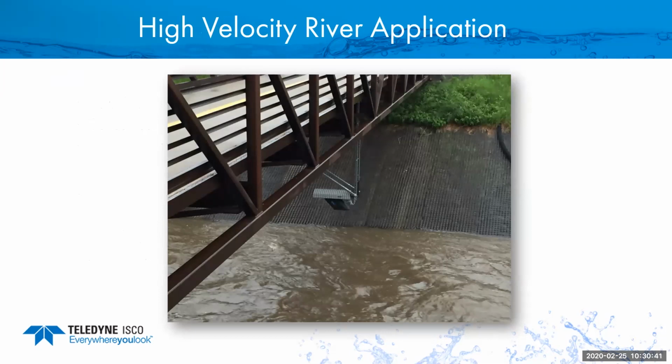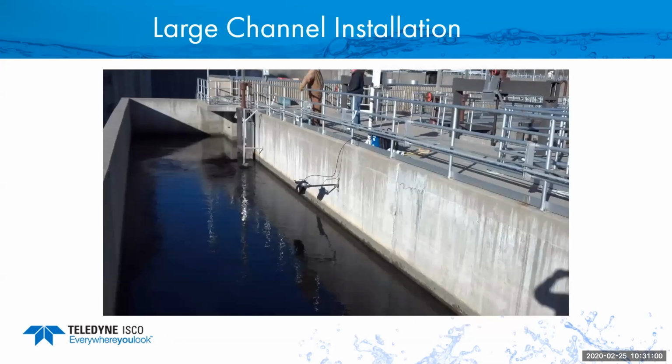You'll notice on top of that one, there is a sunshade. So if you have it outside, you'll probably want a sunshade because of the ultrasonic level, not the velocity, because the ultrasonic doesn't want to get heated up by the sun. So good way to measure this, about the only way you can measure that.